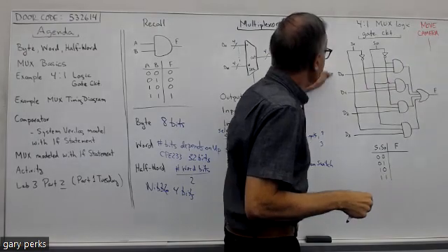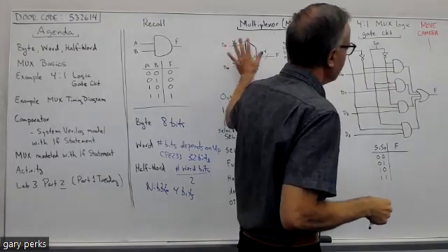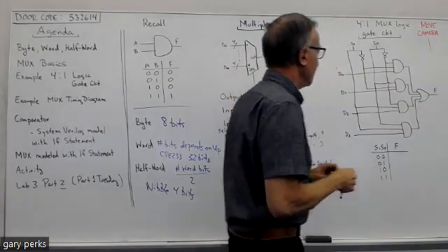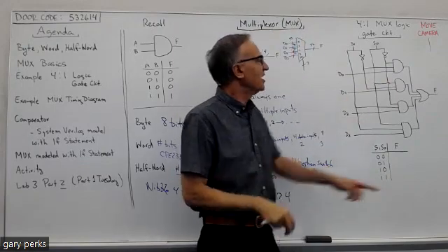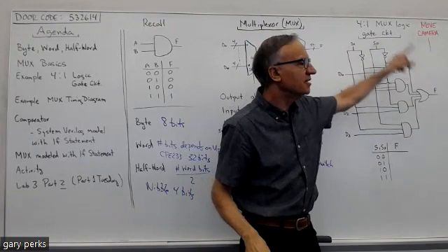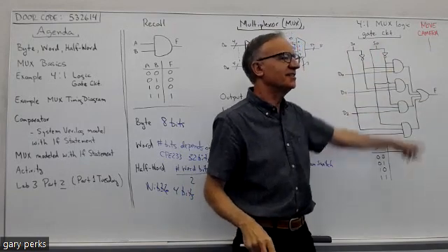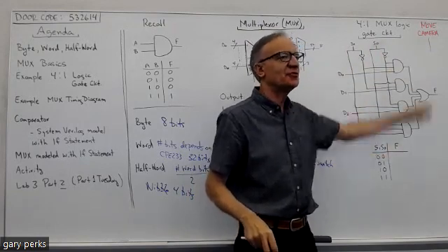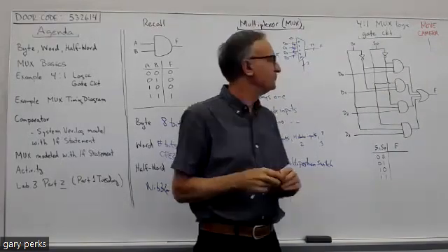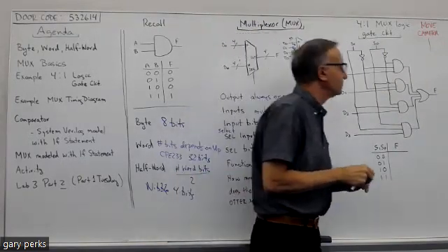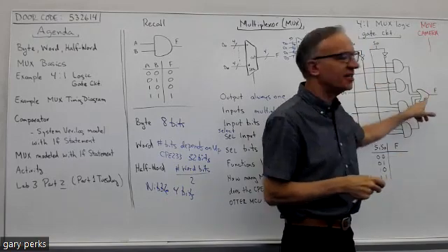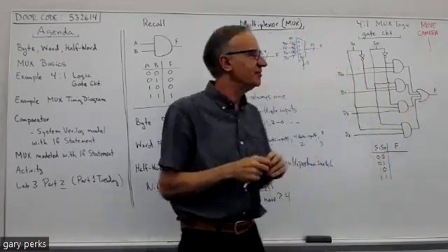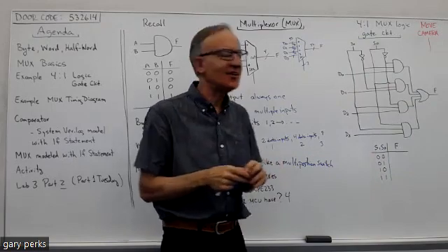So you can see here, I labeled the inputs the same as what I did with the symbol, and I labeled the output the same. Now, here's a little review question. What kind of logic circuit is this? Is this SOP, POS, NAND, NOR? So product, right, SOP, right? Sum of products, because we have the AND gates first. That was just a little review question there.